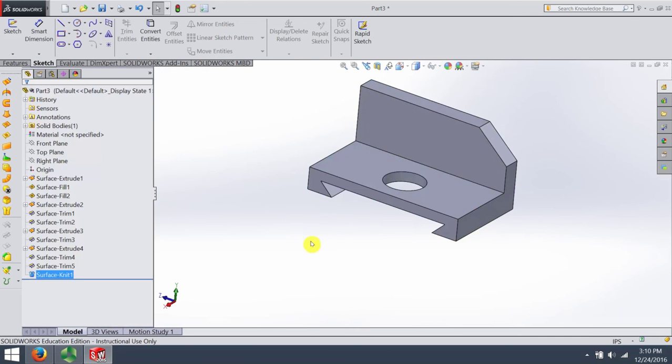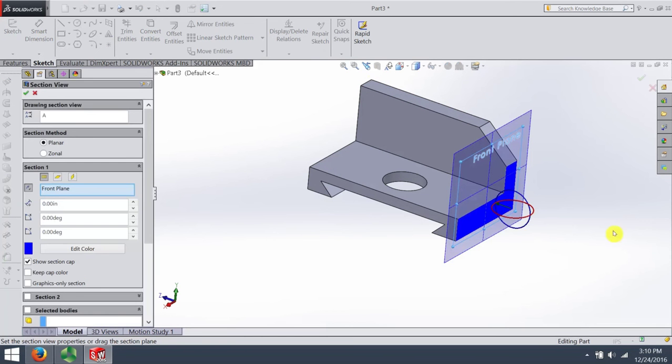By the way, if you hit that and it didn't work, it just means that you have some extra surface somewhere, something that's kind of cutting across inside and you can't see it, or you left a gap somewhere, it's not really tightly sealed at each joint, then yeah, it's going to say I can't turn that into a solid. Okay, so just to prove the point, here it is as a solid.